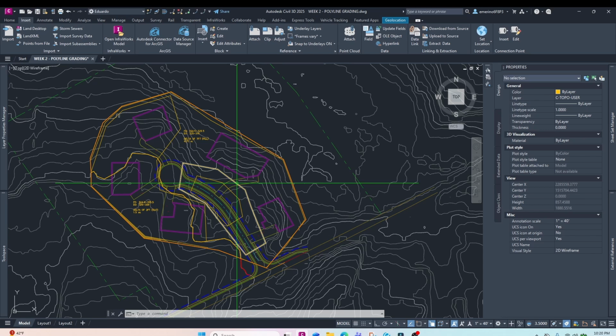It starts jagging all over the place. And it's because, again, these automation tools are fairly new. So the software, the coding that CAD has, it's pretty good, but it still has its bugs. It still has its flaws. So sometimes it can't handle all that data, especially when you do intermediate points everywhere.